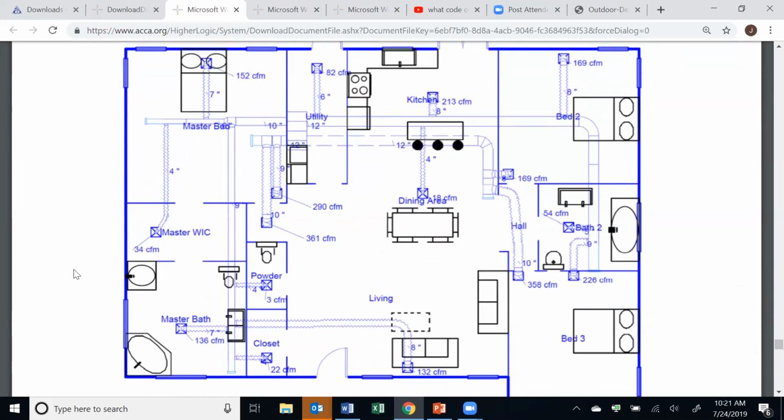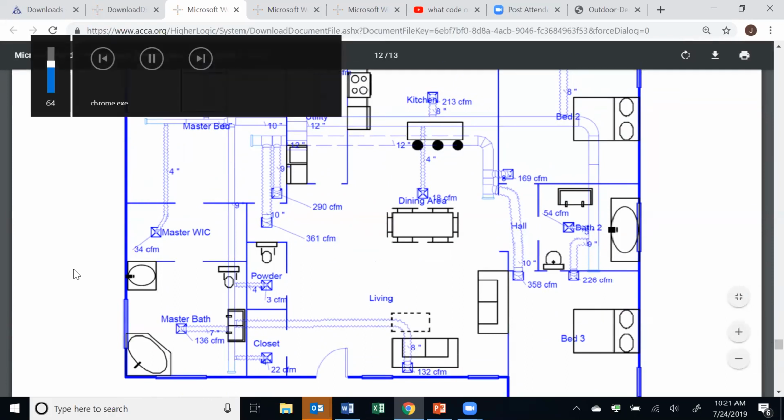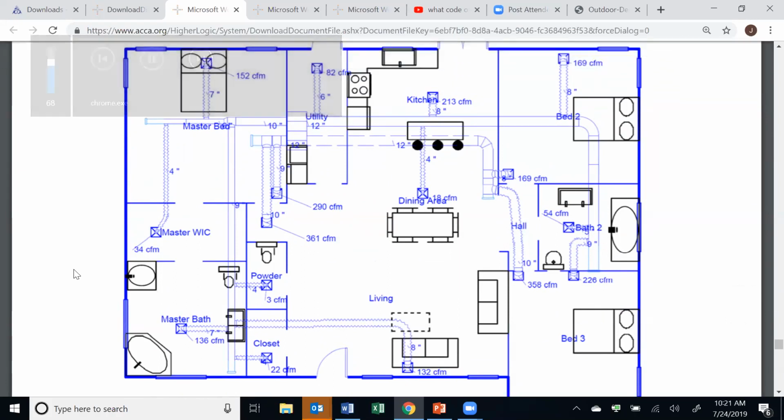At the plan review stage, you can pull out your ductulator or duct calculator and spot check some sizes. The one word of caution that I would add is, if you get a different number, have that discussion with the contractor. There are software tools that will actually calculate the size of each branch run based on those formulas we talked about before.